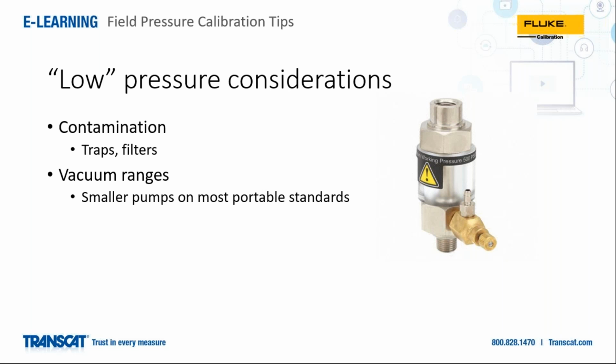I get a lot of questions about filters. Hey, can I stick a filter in here and will that help? And the answer is yes, it will, but a filter is a restriction in the pneumatic circuit, and a restriction creates a pressure differential.